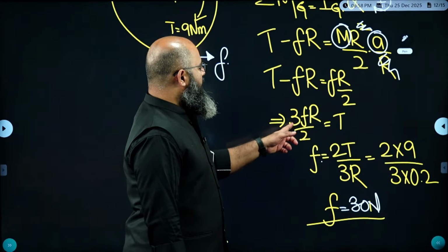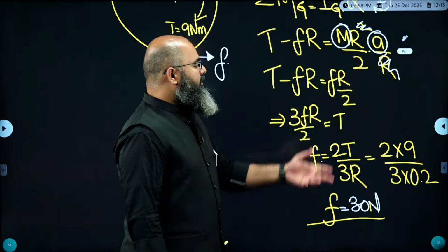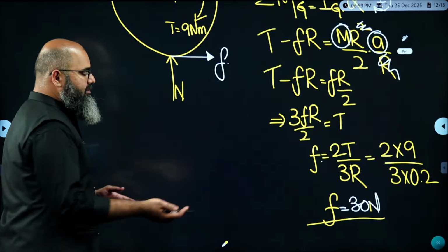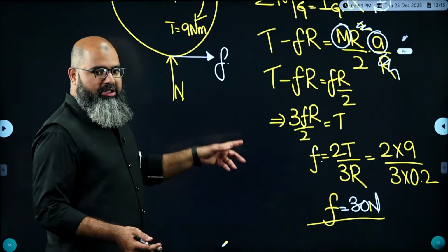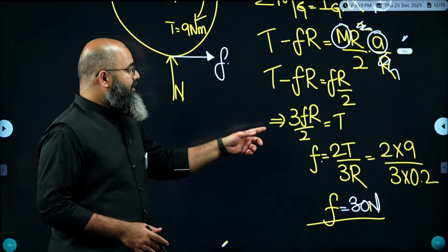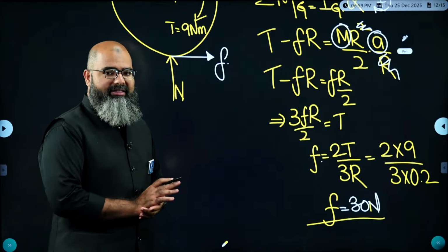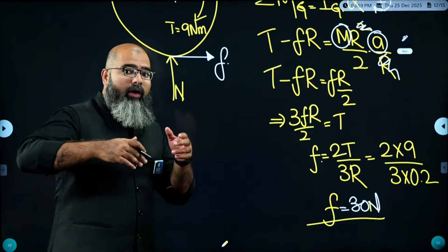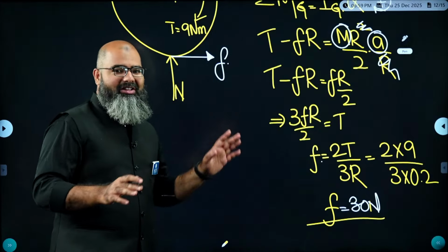One second. So answer of torque will be equal to 21 Newton meter. That is the maximum value. So I can create a multiple set question also. It will become very complex. In such a case, the maximum torque is equal to 21 Newton meter. If you go beyond 21 Newton meter, then slip is taking place.